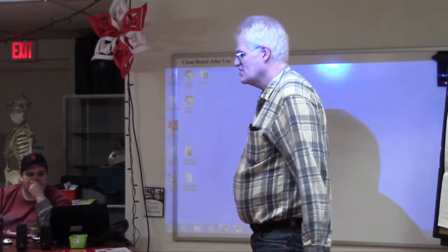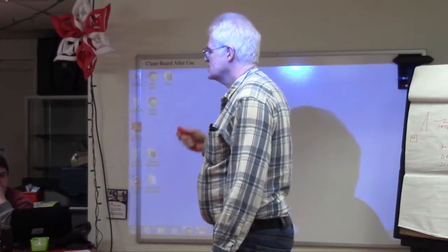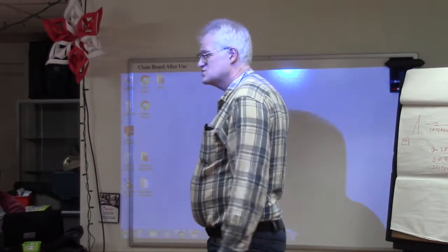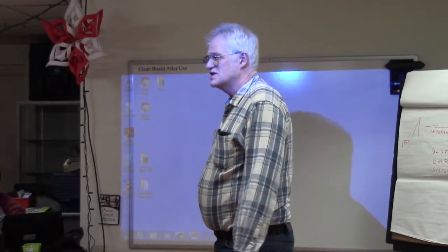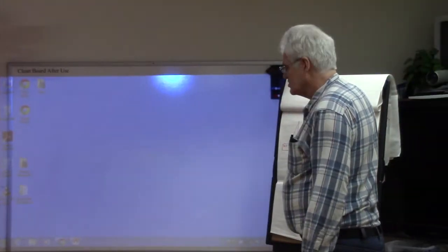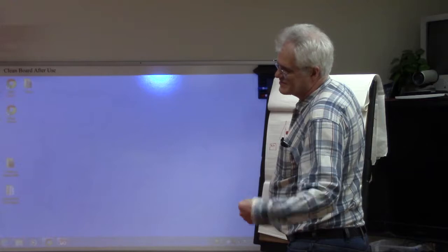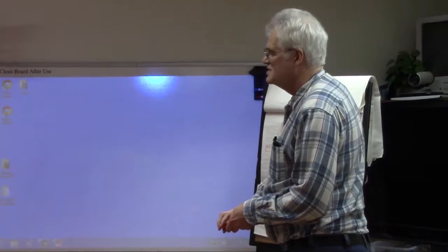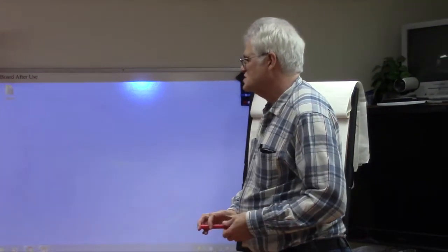I'll talk very briefly about areas and emergencies. Locally, for most cases, especially with Red Cross people, if we ever have an emergency in the city and the telephone service was to go down, amateur radio would be the place, because if you're setting up evacuation centers in the city, that's going to be your means of talking between the office here and the various functions. Generally, you would most likely be going through repeaters, or in the very worst case, working simplex. But you would still have communications locally between your various operations in the city.